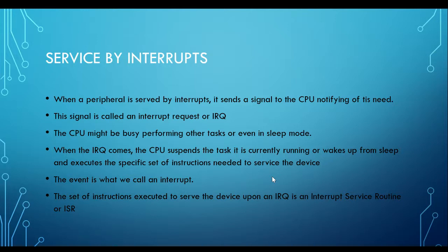Okay, now when it is being served by an interrupt, it sends a signal to the CPU notifying of this need. The signal is called interrupt request or IRQ. Okay, it can be a pin. It can be a pin that when there is a signal coming, it resets the pin value so that the CPU can actually detect, okay, this pin value is reset or set. By that, we know that there is an interrupt request. Okay, so the CPU might be busy performing other tasks, or even in sleep mode.